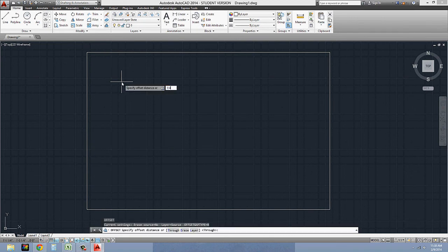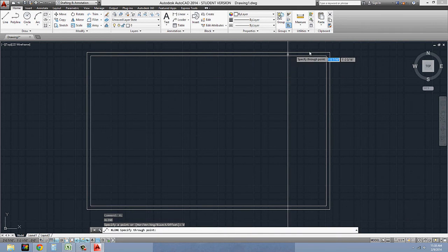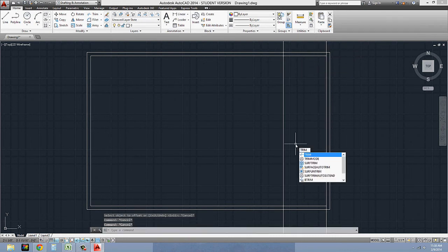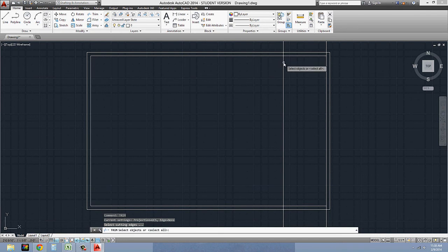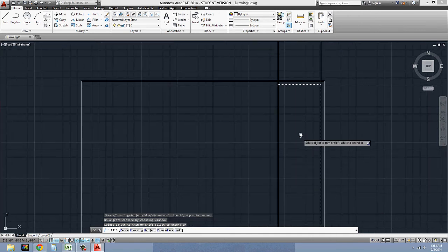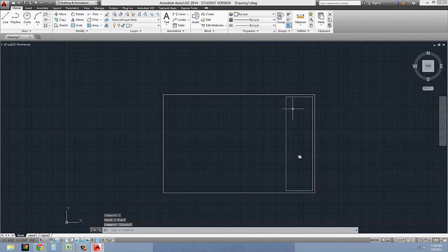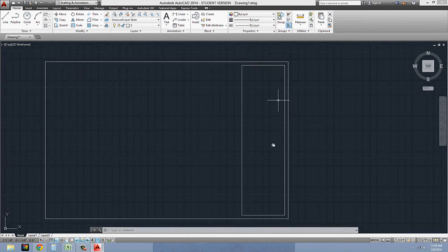So I'm going to offset this rectangle by a 1/4 inch. Then I'm going to offset that 3 inches, and that's going to define my area in which I'm going to have my firm information, my drawing name, drawing title, all that information. I'm just trimming it away, and that's going to be the area that has all of that. All of my drawings are actually going to sit in this other area, so I don't want to take up too much space with the title area, and I leave the majority of it for my drawing space. So this is essentially what you should set up.